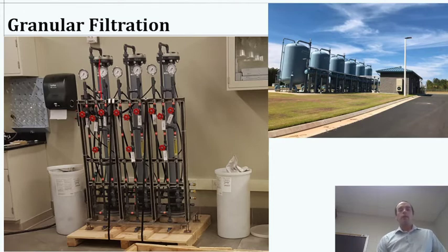Essentially, we have 3 columns here. Each of these contain granular media. This particular unit is more often used for iron and arsenic removal, but it is the same principle in terms of a granular filtration media. So this is less designed for particles, although it would remove some, and more designed for stuff to stick on, like I was talking about, the Brita filter. It's a little more of that style where we want chemical adsorption.